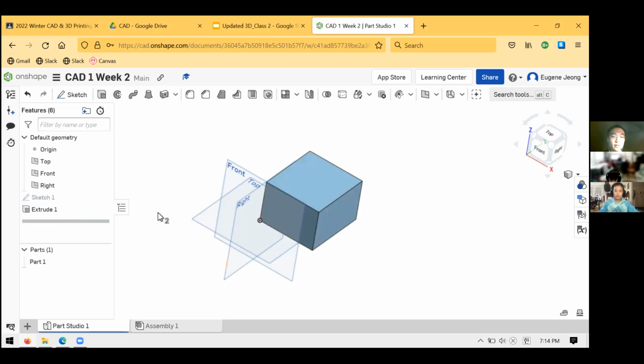And as you continue to create things, I could now at this point create another sketch, and I could do another extrude. I could create another sketch after that, and I could work with one of these other tools. And every time I create a feature or a sketch, it'll add itself chronologically, in order of when I did it, to this feature tree. You can think of it kind of like a list, a record of everything that you've been doing. So first there were the default things, the top, front, and right planes and the origin, then there was sketch 1, then there was extrude 1.